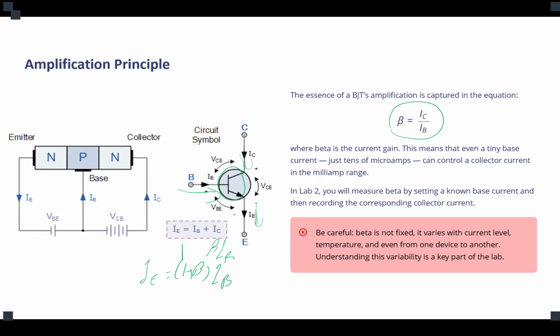That is important when you want to design and calculate the amount of resistance that you connect to the emitter, because now the base sees (1 plus beta) times that resistor, not just beta times that resistor. And since normally we use a high amount of resistance, that 1 is quite a number. Is that clear? Are we good?